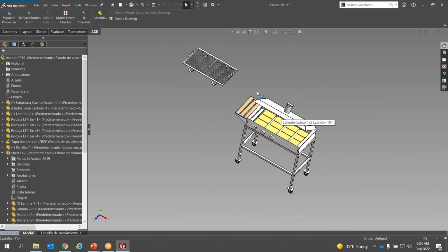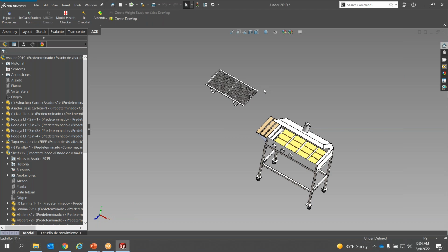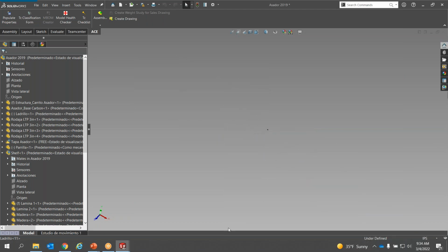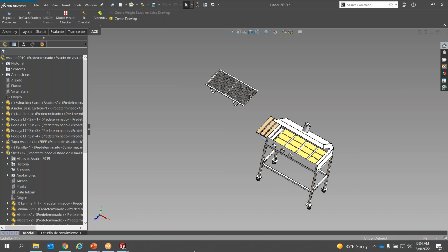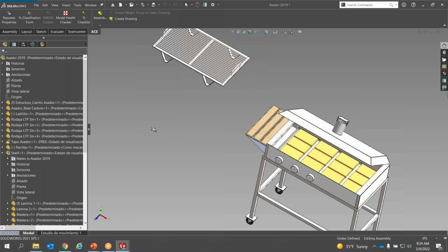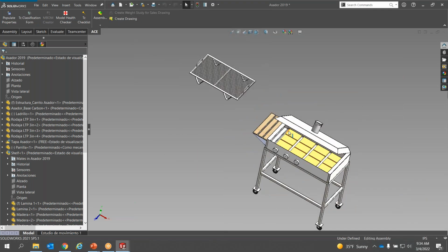My zoom command, like, oh no, I bumped my 3D mouse. Now I can't see where I'm at. I can double click the mouse wheel and zoom back in, or we can hit the F key and it'll do the same thing. You could do your Shift and drag, right click and Shift and drag in and out. That'll just be right at the screen center.